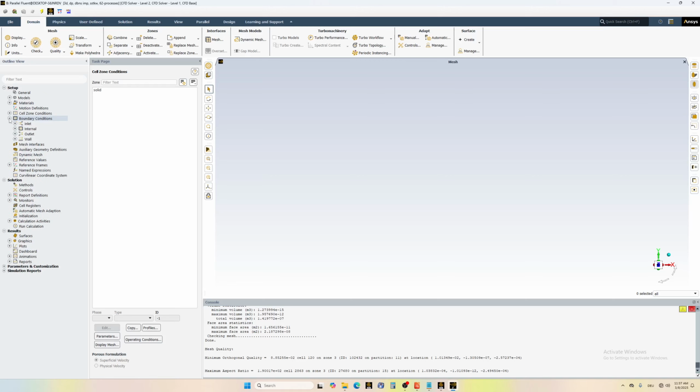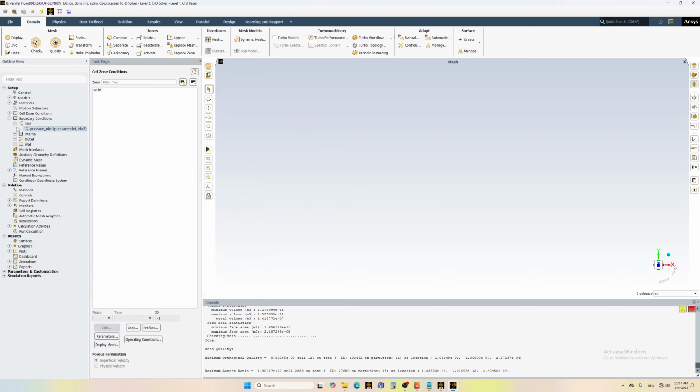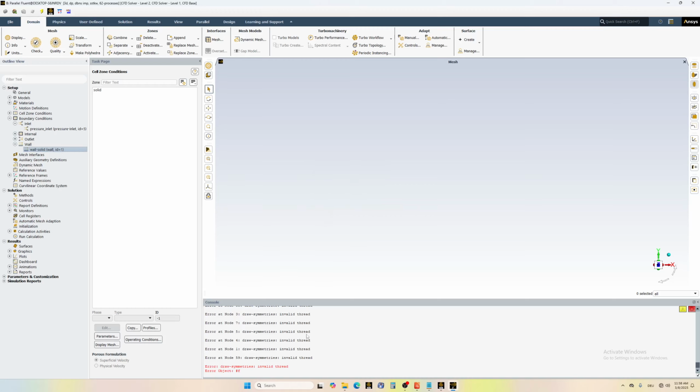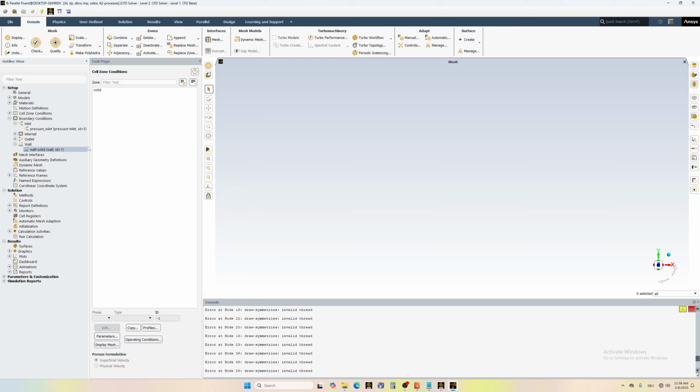And boundary conditions, now here, if you didn't define, you can define the inlet. So the inlet pressure inlet, it's the same as in the axisymmetric case. I will not change it, the same outlet and the wall. So if you right click on this one and display, you can see, or you cannot, because I imported that geometry without changing these settings, but it's fine. Everything is okay.